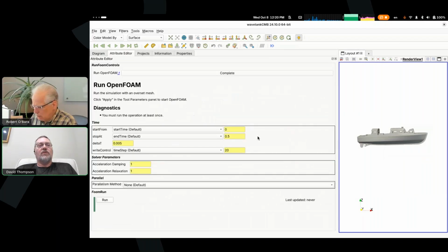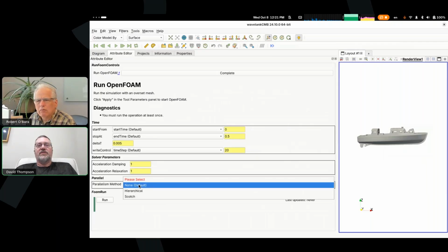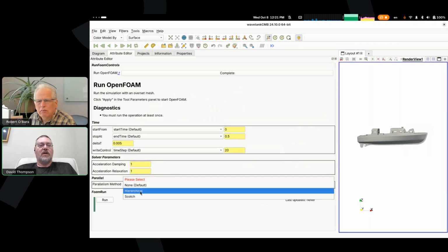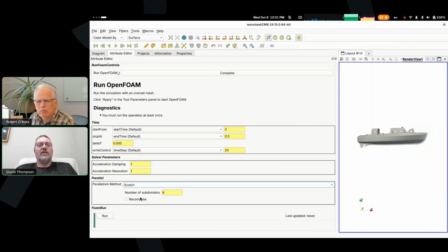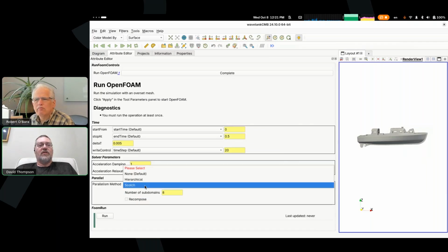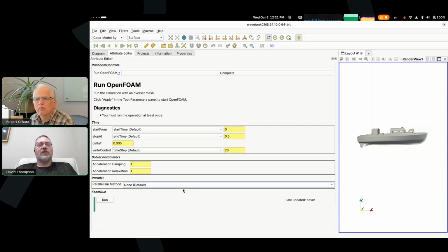And finally, we get to running OpenFOAM, and you can choose to run it in parallel or just on your laptop without running MPI or anything. If you run it in parallel, you can choose the scheme for the decomposition of the mesh, and you can choose parameters like start time and end time and so on. I'm not going to click run here because a meaningful simulation would take a while. But unless I've forgotten something, we'll skip that, and we'll go back to the slides, and you can actually see the results of the simulation post-process.